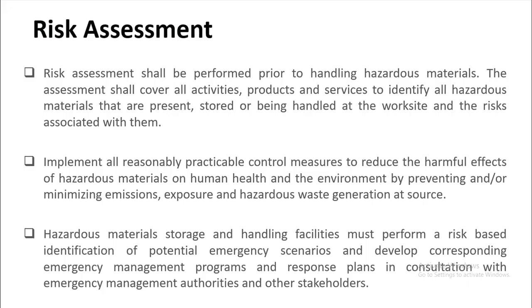Risk assessment. When we are handling hazardous materials, we need to make sure that a risk assessment shall be performed prior to handling them. The assessment shall cover all activities, products, and services to identify all hazardous materials that are present, stored, or being handled at the worksite, and the risks associated with them. Before we receive or order materials to the site, we should have a risk assessment so that when the hazardous materials arrive at site, we already know how to handle them and how to prevent accidents or risk associated with these chemicals.